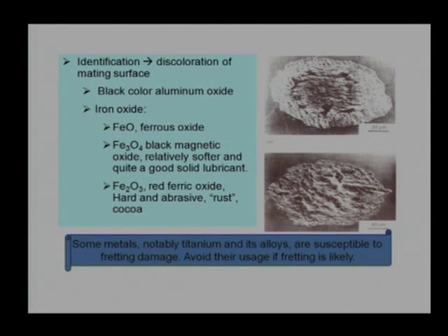And if we understand this kind of fretting corrosion, fretting wear, in this case I am using the word fretting corrosion again, because fretting is the starting point, and when it generates a number of particles, and if air or a medium is available, all those particles will get oxidized.